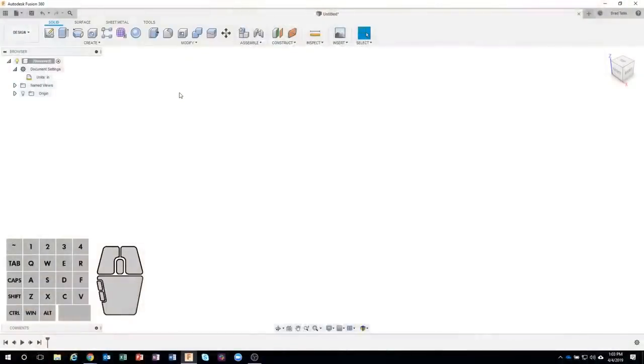Doing a little research, it sounds like back in the day with CRT screens, a scalable vector graphic is typically about 92 pixels. So when we bring in these SVG files, they're going to come in the right size, the wrong size, etc. One tip I use is to create the object I'm going to make first and then bring in my SVG.